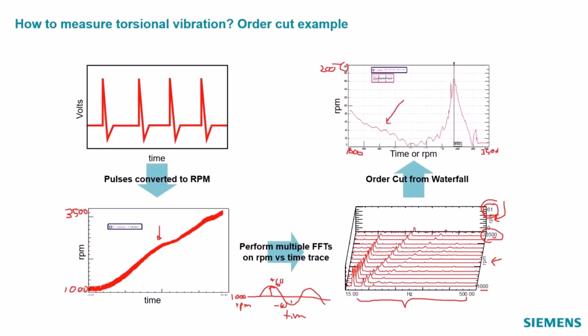Charles, one thing to notice here is as we're going up in speed in this area, what's happening to our torsional vibration? It definitely looks like it's going down as we're going up in RPM. Yeah, it's going down. And that's because the combustion events or the windings, the time in between these things starts to decrease as you go up in speed. So it tends to run smoother. So a lot of things, like hydraulic pumps have these little vanes or little compartments in them, and they cause pressure fluctuations. The higher you go in speed, the smoother it runs until something happened here.